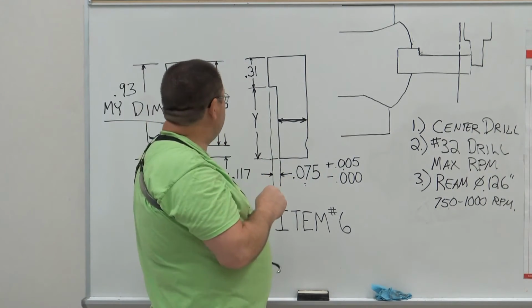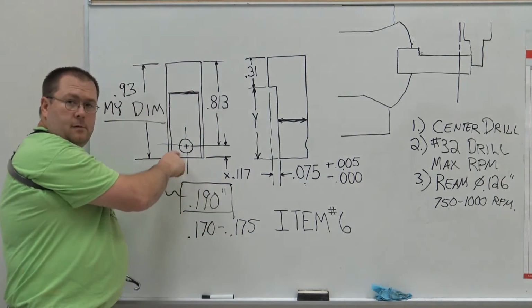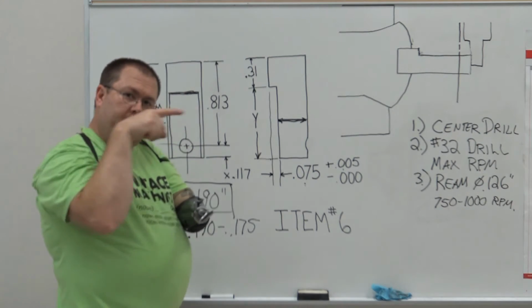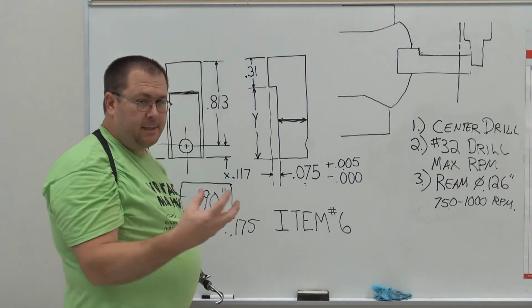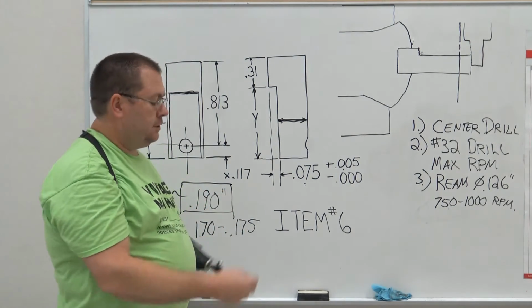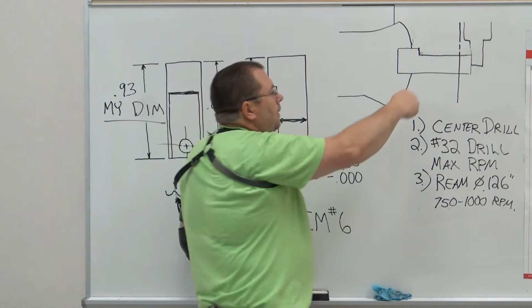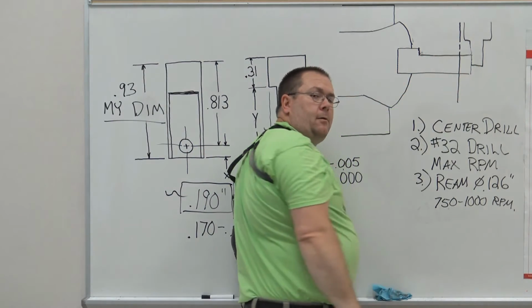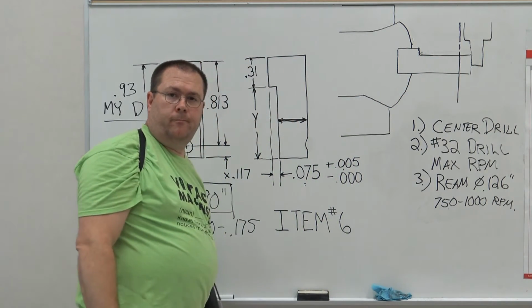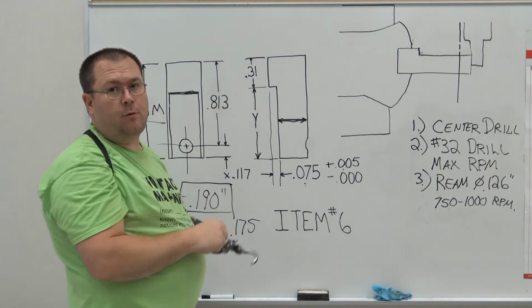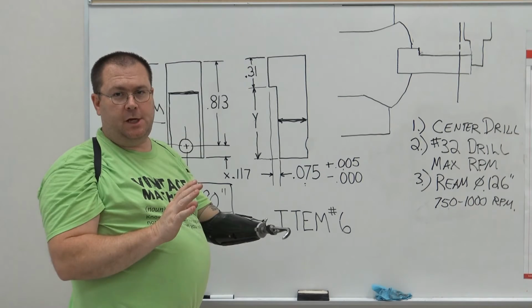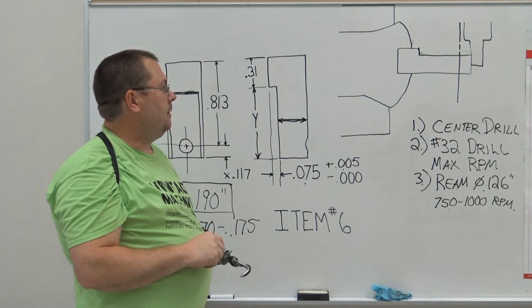The hole that we just put in, this hole right here, receives the offset pin in your crankshaft. So you're going to take your crankshaft out of your toolbox, and you're going to take that little pin, and you're going to place it down inside that hole. Number one, if it doesn't fit, you used the wrong size reamer. That's a good inspection check.